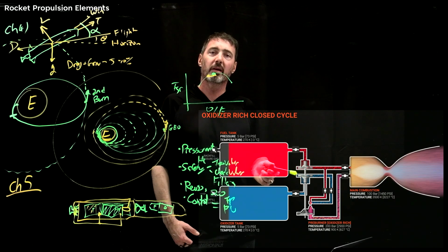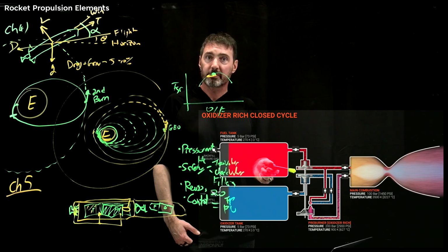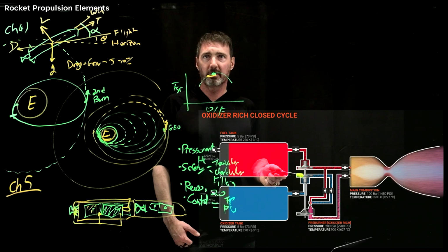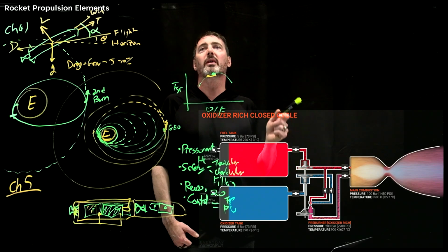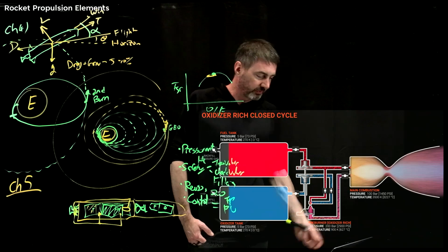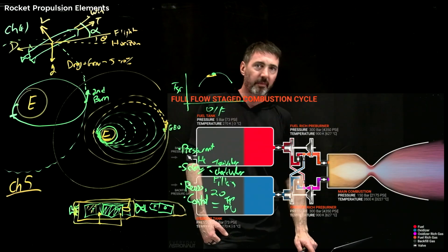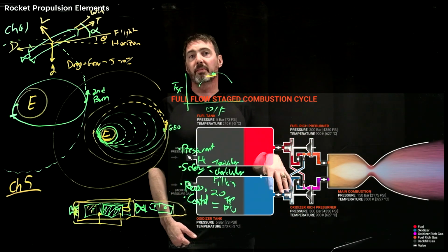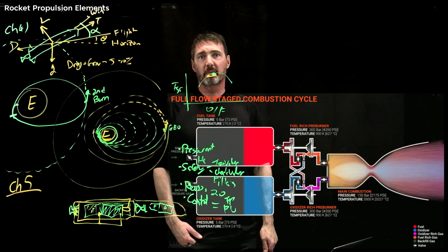So between here, it's called your interpropellant seal in the moving part, but a big failure mode is if you get a little bit of oxygen entering over here into a little bit of fuel, there's enough heat through this kind of spinning parts, you can create a reaction and basically blow up your engine right here. So full flow staged combustion really minimizes that risk, and so it's a pretty awesome process.